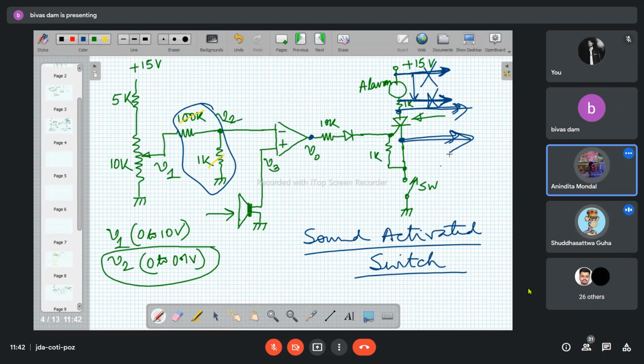Flash will be on. The capacitor will discharge and the flash light will be available. So in that light, whatever things are visualized, that image will be captured by the camera. So we can get one mid-air image of the fired bullet in this particular method.